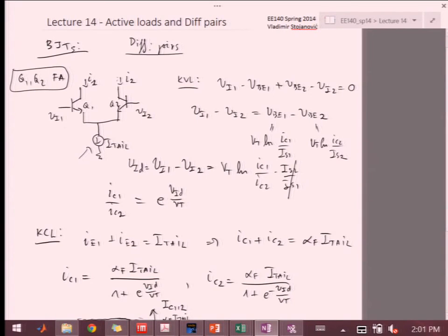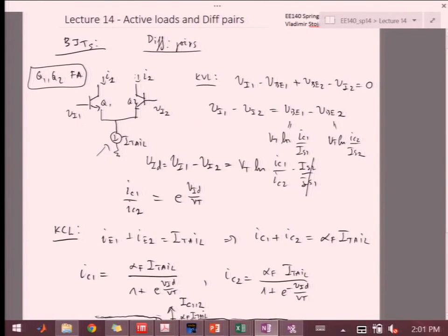You mean here? Well, here it's only going to start pushing collector down. But it's not directly dropping VID across it, right? If I have a very large VID, I need to spend it somewhere so that only a fraction of VID gets dropped across VBE, right? So take a look at this equation, right? This is the equation that determines what amount of VID gets dropped on the VBEs, right? Can I insert something there to sort of absorb all the VID?